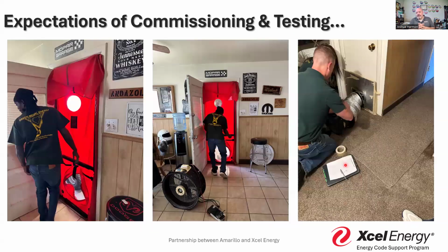So when we think about when we see these out in the real world, right? These are some pictures of some that we did here recently. So again, we're out doing blower door tests to verify, are the systems in place in residential homes? So this is how we know. Is the envelope working? Is the mechanical system the problem? Here they're installing another duct blaster onto a mechanical duct system. So we can see where those leaks are taking place and make that home more efficient.